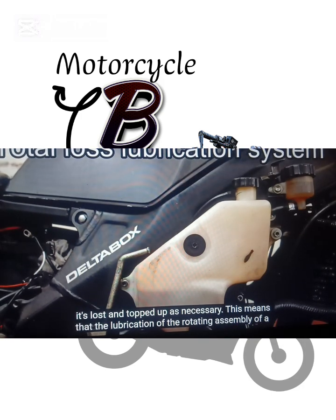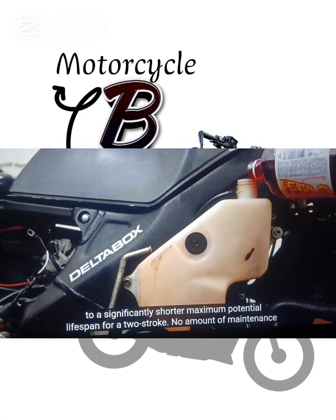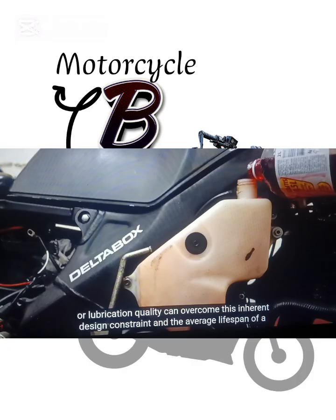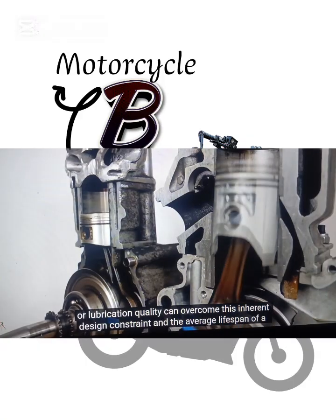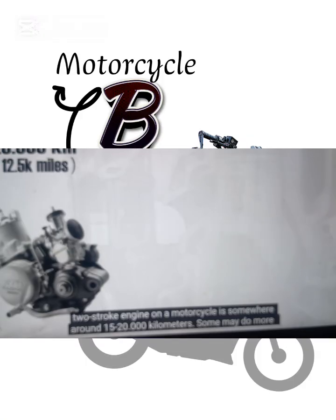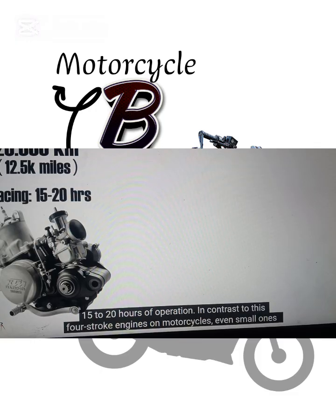This means that the lubrication of the rotating assembly of a two-stroke isn't nearly as consistent or reliable as in a four-stroke engine, which ultimately leads to a significantly shorter maximum potential lifespan for a two-stroke. No amount of maintenance or lubrication quality can overcome this inherent design constraint, and the average lifespan of a two-stroke engine on a motorcycle is somewhere around 15 to 20,000 kilometers. Some may do more than that, but many won't make it even that far and will need their pistons replaced and bottom ends rebuilt well before that. Racing two-stroke motorcycles often need rebuilds after only 15 to 20 hours of operation.